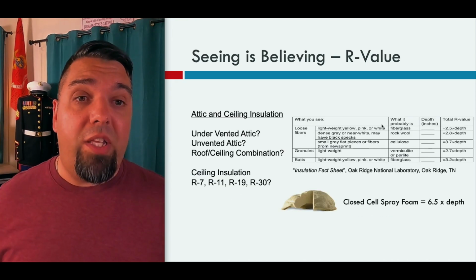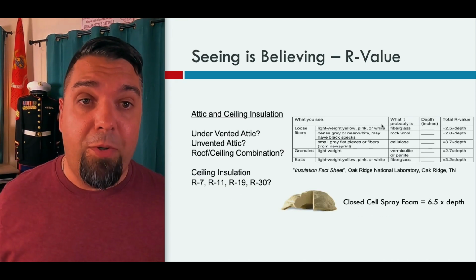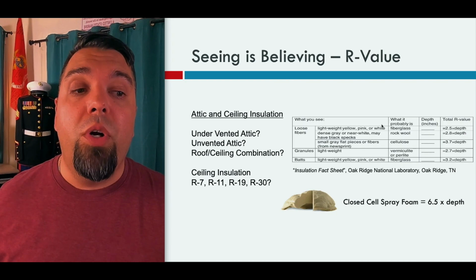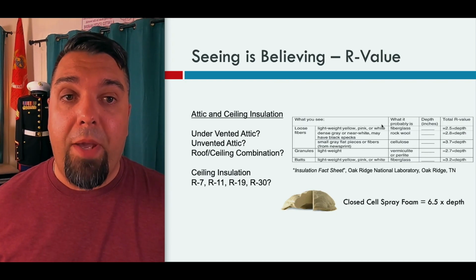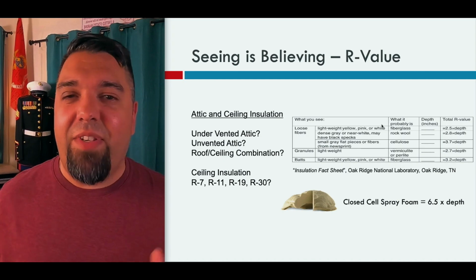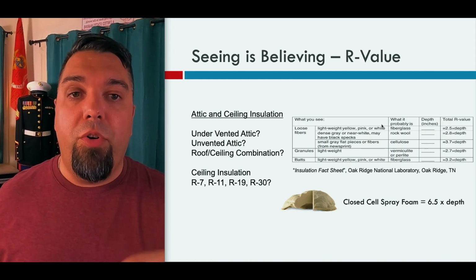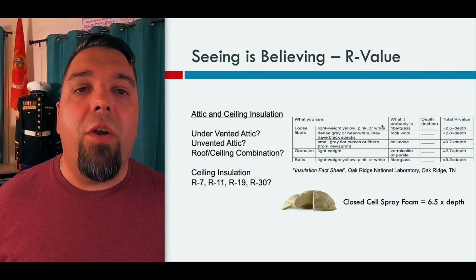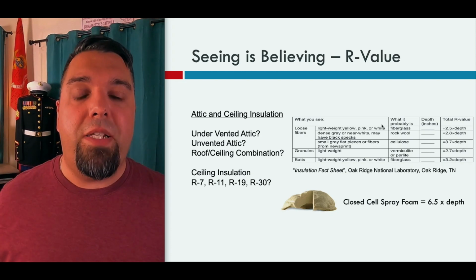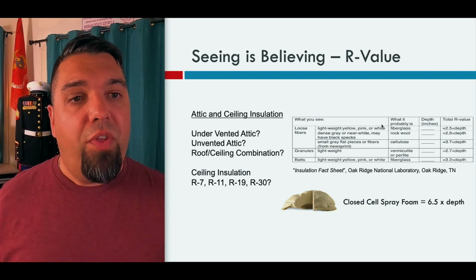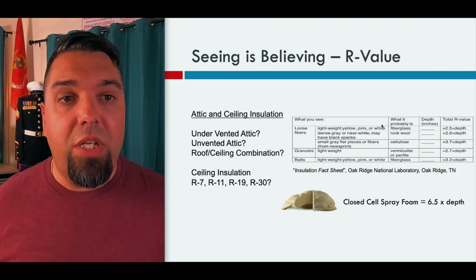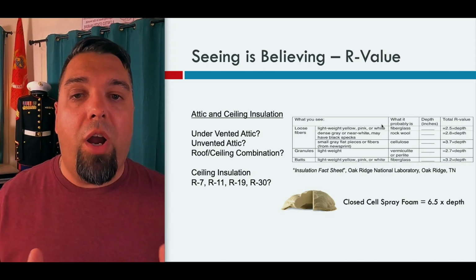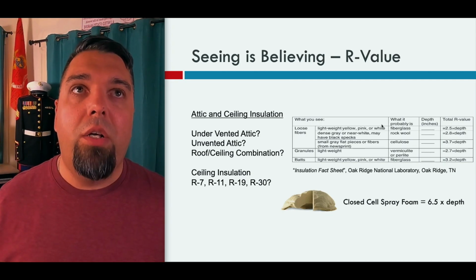If you don't know what the R value is supposed to be, because you are supposed to be looking at this on the site, obviously if you're one of my elite members, you probably walked through the site survey course that we have available on Patreon. It's the first, let's say, 7 to 10 videos in numerical order. If you've been through that, you've probably seen this chart. This is a great chart from Oak Ridge National Laboratory, and this is basically what you see and you measure the depth, you'll know that per inch is the R value on the right-hand side, and you can figure out what the actual total R value is for the insulation, let's say in a wall or in a ceiling.